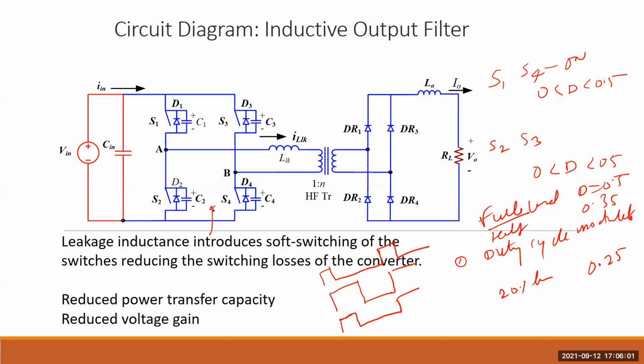Okay. So if this duty cycle changes, what happens? The purpose of changing the duty cycle is to regulate the output voltage and control the power flow. So to regulate the output voltage when the load changes, or to control the power flow, you have to block or unblock the circuitry for some time, and blocking and unblocking is done by the switching.